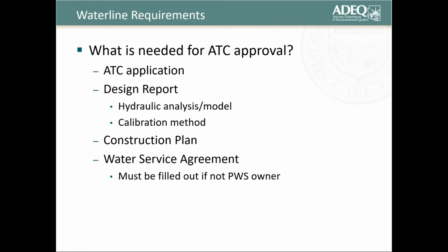Some common deficiencies that I would like to point out for waterline applications: it's usually that the ATC application is not completely filled out. There are some sections on there that are not filled out. When it pertains to a waterline, we like to see that it's completely filled out and all the necessary information is on there.